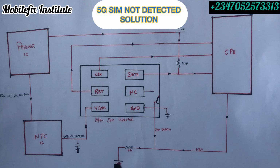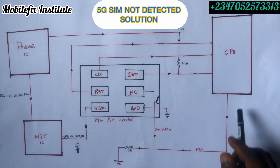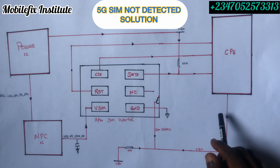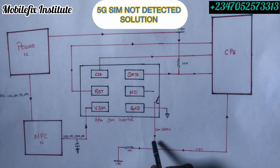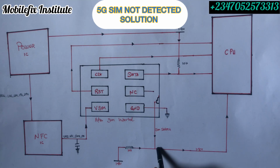You will get your 1.8. Test this side also. If it doesn't give you a value, know that it's open from our CPU side. So you have to trace this line and locate where it's open, and then run a jumper. Now this other side can also be open, you see. So it's very, very important to test this line also.